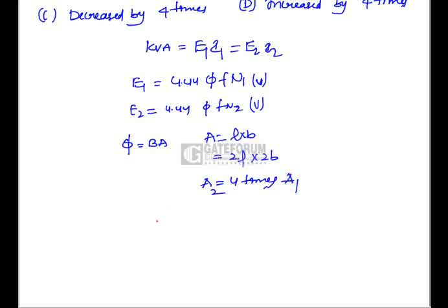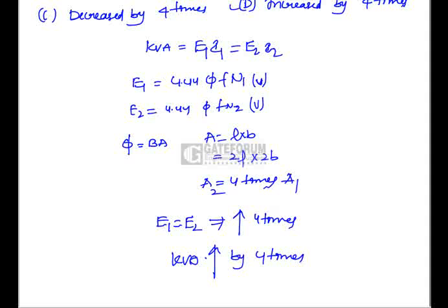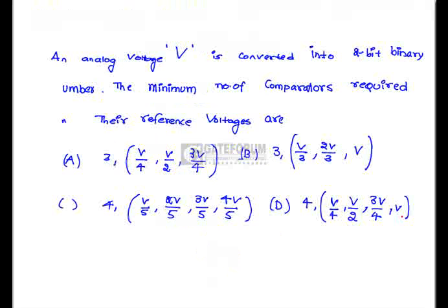Now what is induced EMF E? Induced EMF E1, which is equal to E2, is increased by 4 times. If induced EMF is increased by 4 times, what happens to the kVA rating? kVA rating is increased by 4 times. So the option is D.